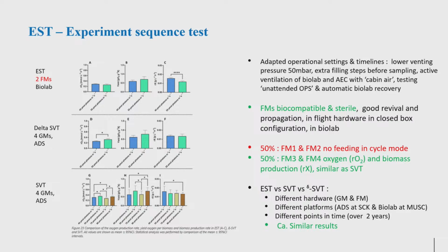Gas chromatography people doing autosampler and companies know this very well, that you should use needles where the hole is at the side. PD didn't know it. We never asked what kind of needle was on it, but then all of a sudden, if you start using new septa, you discover it. No design change possible, but okay, there is polishing on the needles. You reuse the same septa because then your risk of these events is smaller, and so you find workarounds.